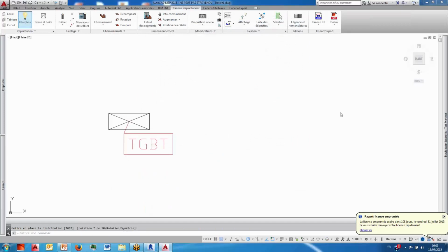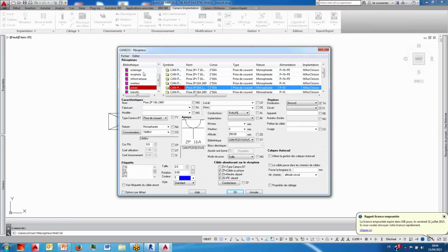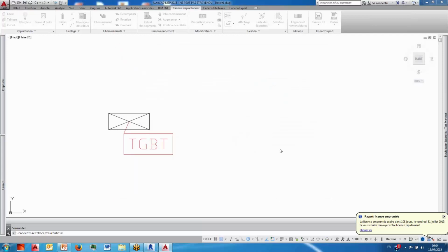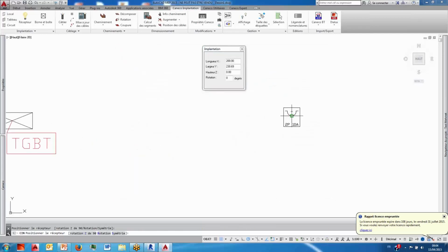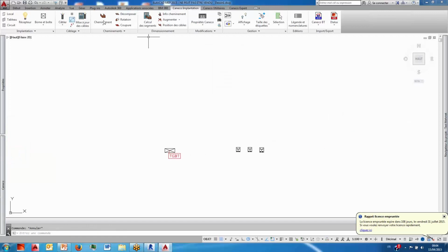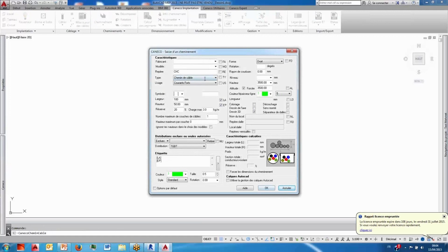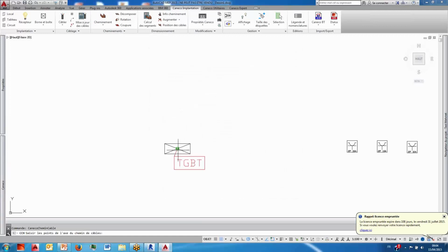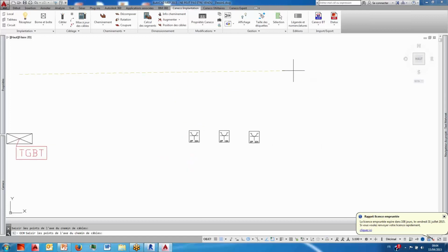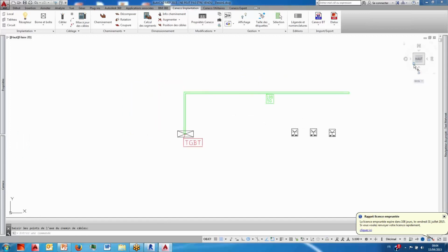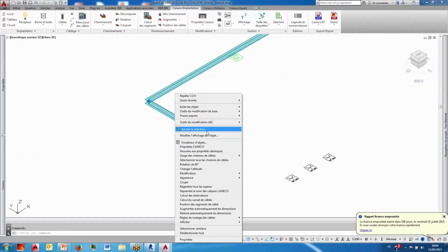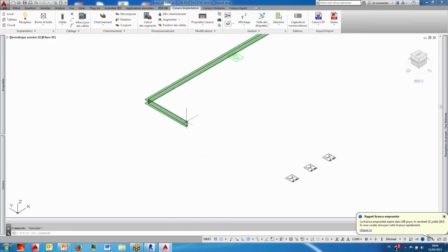And you can say, I want new equipment. You can select circuit, so you have a view of the different kinds of circuit. It's based on DWG, and that can be in 2D or in 3D. So you can also create cable trays. Just select the tracks and just create them. Very simple to work on the AutoCAD platform. So you just create it, and you can also have a 3D view. You can create the verticality, the vertical cable trays, if you want or not.